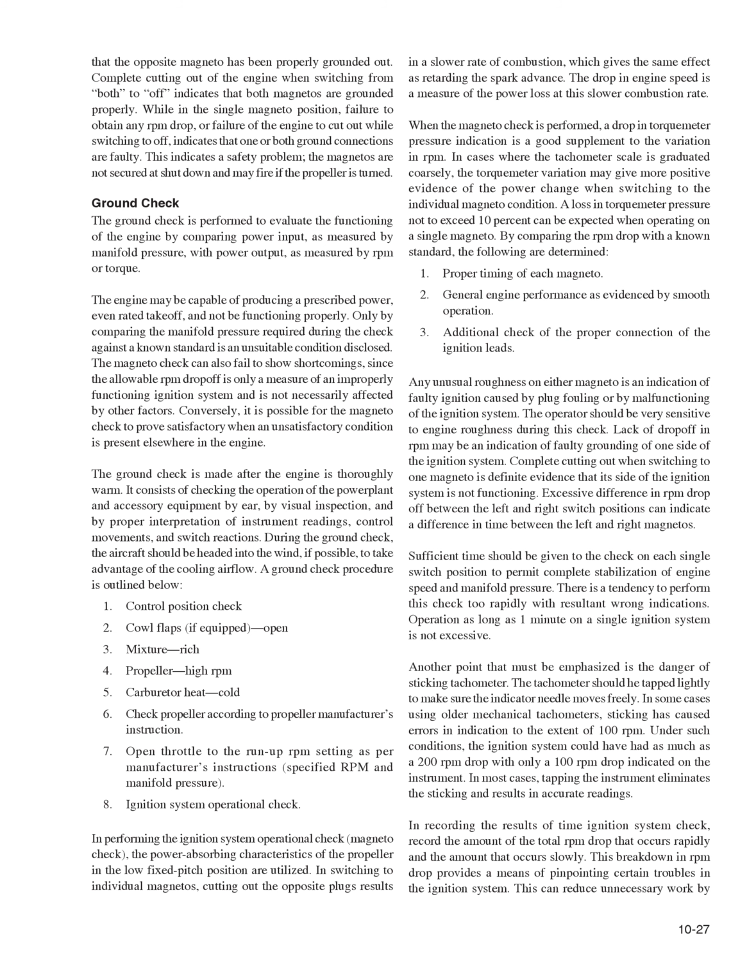By comparing the RPM drop with a known standard, the following are determined. 1. Proper timing of each magneto. 2. General engine performance is evidenced by smooth operation.